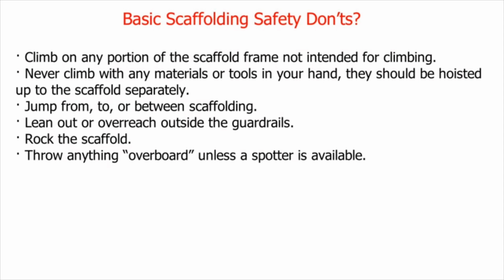Jump from, to, or between scaffolding. Lean out or over each outside the guardrails. Rock the scaffold. Throw anything overboard unless a spotter is available.